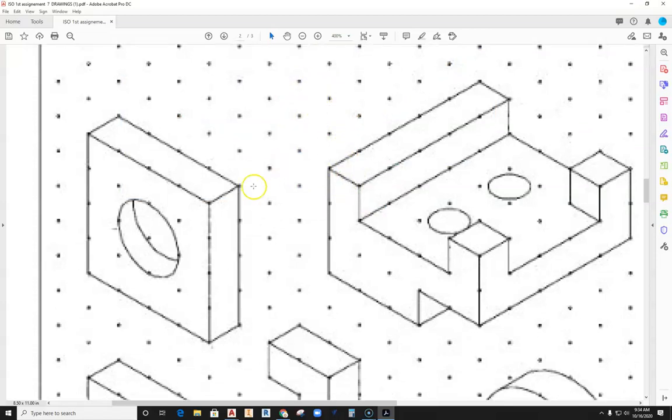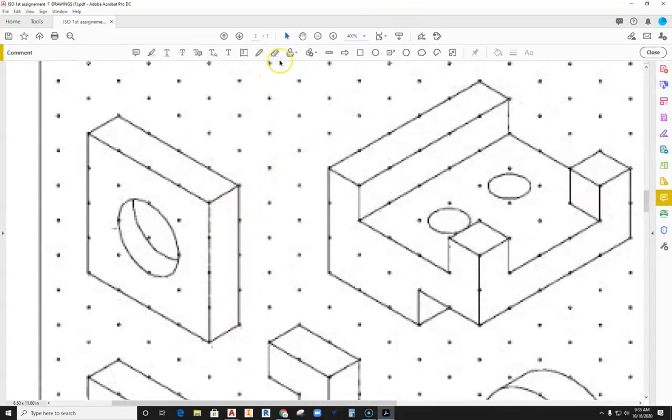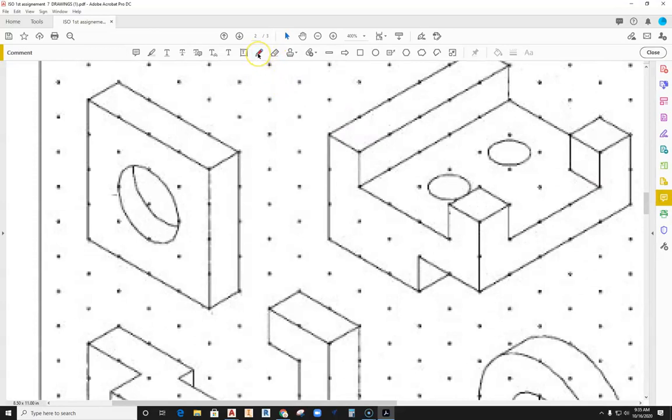Now, that being said, you can only measure along these axis planes, and that's what I've talked with you guys about before, how to do that and how you can only draw on those planes. Well, if I were to use my drawing tool, the distance from this point to this point is obviously a ½ inch. So we would draw this ½ inch line back on the isometric axis, and then we would start going up. And we start counting: 1 point, that's 2 points, that's a ½ inch. Then there's 1 inch, 1.5 inches, and then 2 inches.